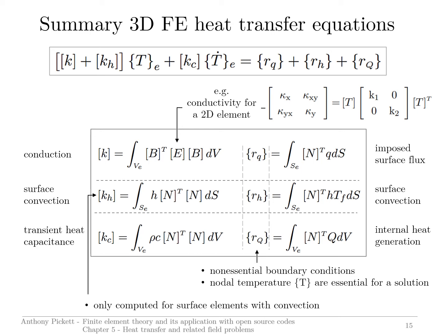If we look at the governing set of equations up here, some of this we've already met, some parts are new. I'll go through each. So far we've met this conductivity matrix for an element. It's given here. It's very much the same as the elements we used in mechanical analysis. The B matrix is exactly the same. It depends upon the element we select.